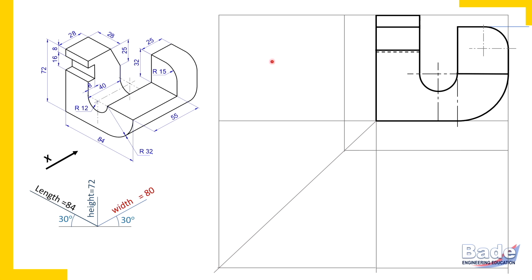But exactly behind this corner, when you are watching from front, exactly behind this corner there is a corner, and from this corner there is a vertical edge. So that vertical edge is from top to bottom. So we are drawing that edge which is hidden. And this is that vertical edge.